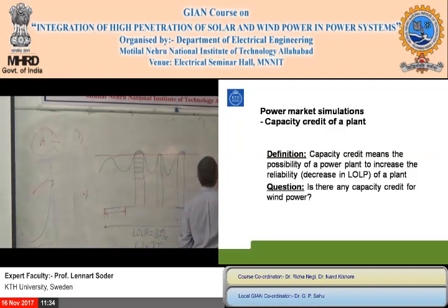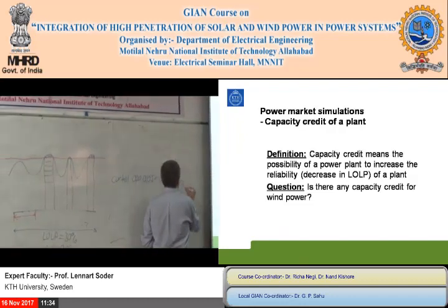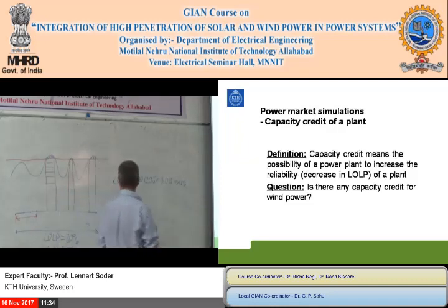Curtail 0.3 times 0.05 is equal to 0.015, which is 1.5%. So we curtail 1.5% of the energy. That energy reliability is equal to 98.5% in this case.